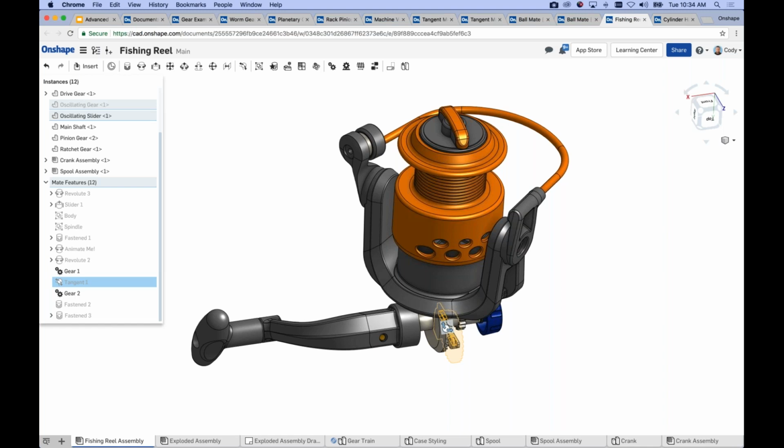The follow-up to that, the weld gun and cylinders were not touching. Should they have been? They do need to touch, and that's a very good point. So the question was, in this example, he's using weld guns and a cylinder. Do they need to touch? And it is, yes. Tangent mates, the faces need to touch in those examples. If they don't, there may be other ways you can mock that up, but using something else like edges or vertices. But if you're selecting faces, they need to touch.